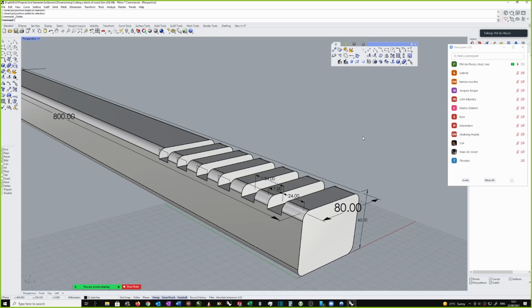No, I suspect that, and as I've said before, I think the problem is that because SolidWorks and other programs allow you to put dimensions in at will, and because you're faced with a shape and you can put dimensions in, you put them in, and then it becomes more and more difficult to figure out whether you've started at the right point. This is what you've got to do: you've got to go at it systematically. So I wonder if maybe we should have a look at one of your projects and see if we can't dimension that step by step.